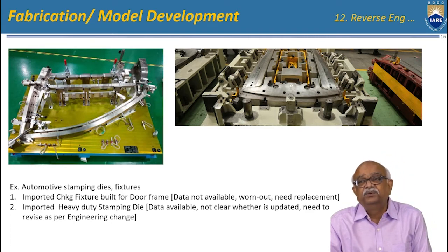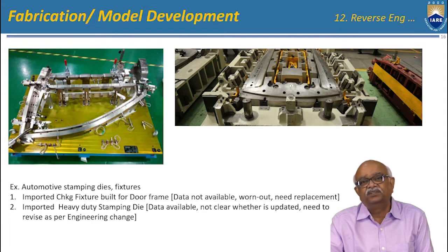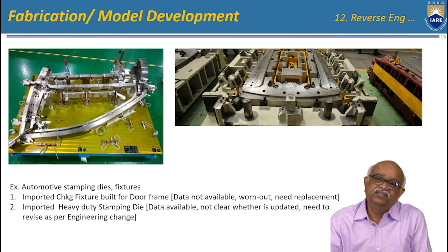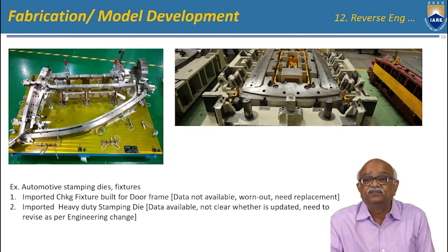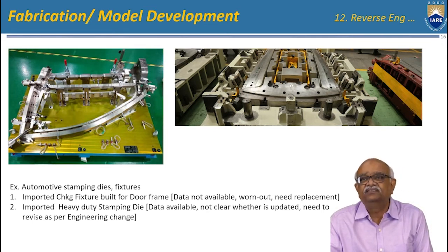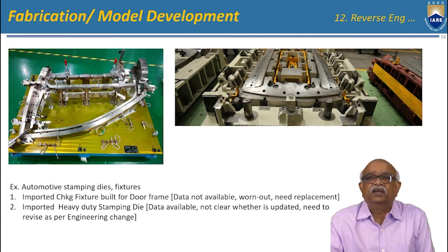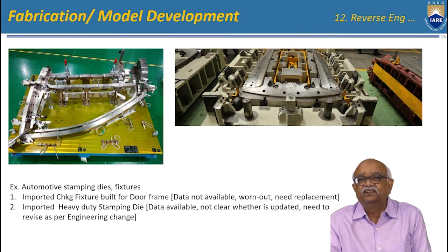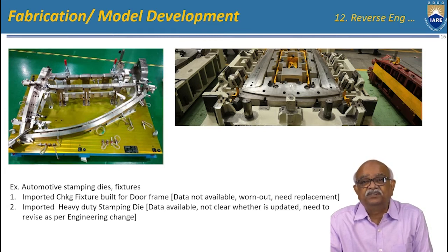So what you will do? You will take the existing tool. You will take the measurements from CMM, scanning, laser, all those things. Then whatever way you want, you create one more drawing, and with the drawing you do the modifications. These are two important things. Day in and day out will be happening in the industry. So that is reverse engineering; without reverse engineering methods, it is impossible.